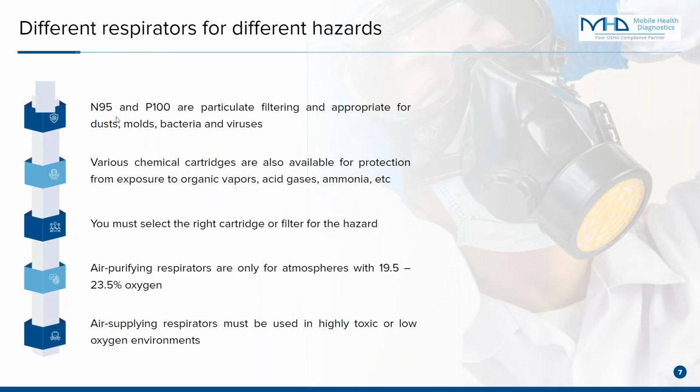Most manufacturers have a list of the different cartridge options available for their respirators. So if you have a specific type or brand of respirator, and specific contaminants that your employees or people wearing respirators could be exposed to, it's best to either reach out to the manufacturer directly or to the vendor that you purchased the respirator from, and verify that the cartridges you're selecting for your employees will actually filter out or be effective in keeping your people safe from the hazards that are present.